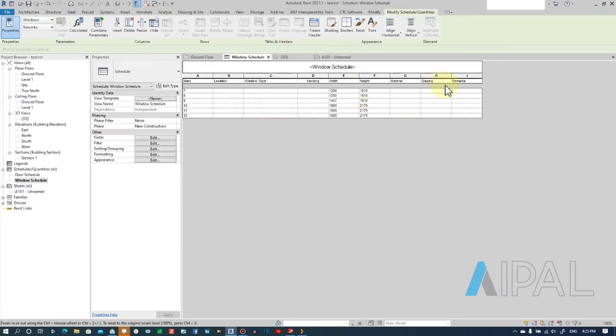The other thing that is problematic with Revit is the ability to deal with text. Typically, this window here, for example, would be labeled as a 1812 window. It takes the first two digits of a 4-digit string. So I guess that would potentially cause an issue if we had a 900 window or something like that. But once again, we can actually deal with that.